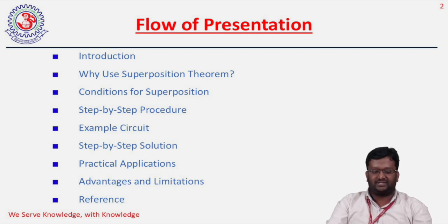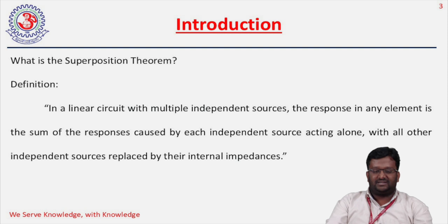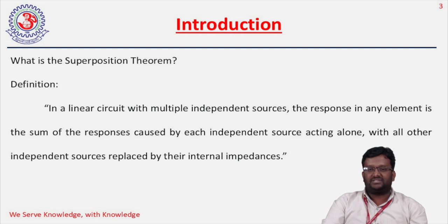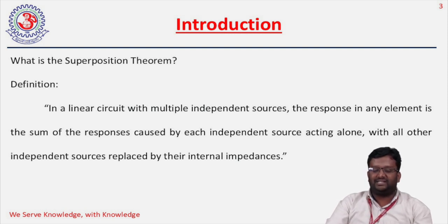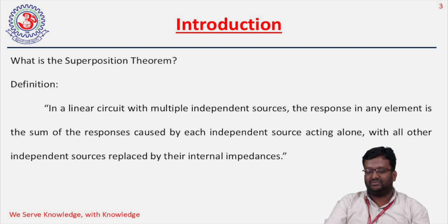That will be the introduction. The definition, which represents, in a linear circuit with multiple independent sources, the response in any element is the sum of the responses caused by each independent source acting alone, with all other independent sources replaced by their internal impedances.